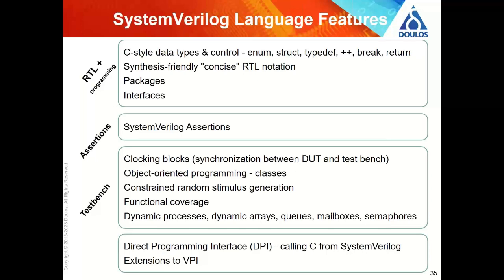There's a separate part of the language which is purely used for assertions. Some people write SystemVerilog assertions to verify VHDL designs, and that works. And there are testbench features, things like classes, constrained random stimulus, functional coverage, and so on. And there's also the interface to C.